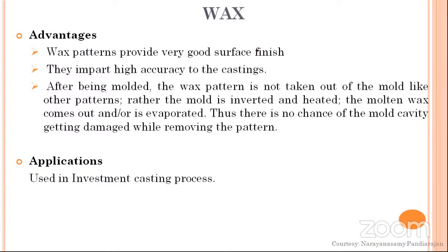Everything has its own advantages and limitations, and it depends upon our end requirements, based on which we have to suitably select a particular pattern material, and the process involved, whether we are going for sand casting or metal mold casting or die casting, whatever it is. So the selection of casting process, the selection of pattern material, everything depends upon the end requirement. We have to compromise on one or the other.